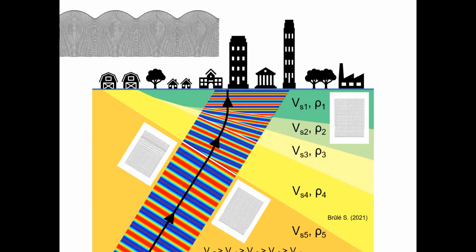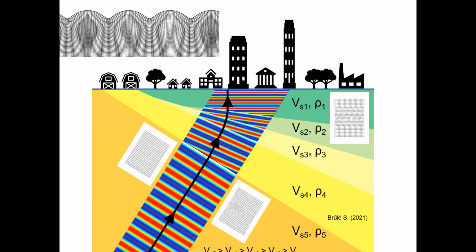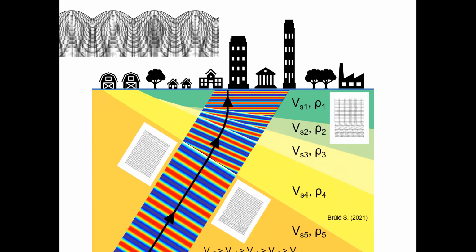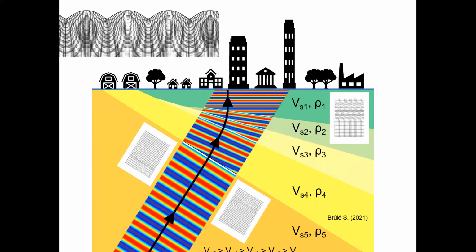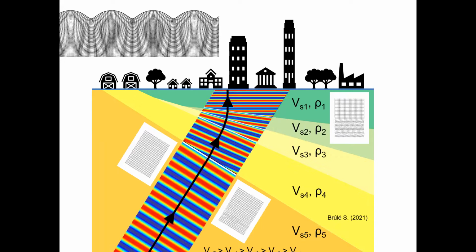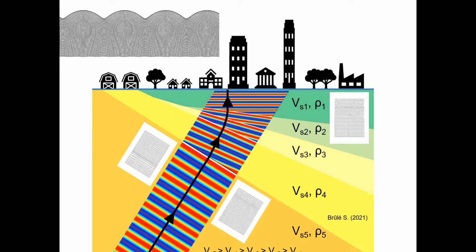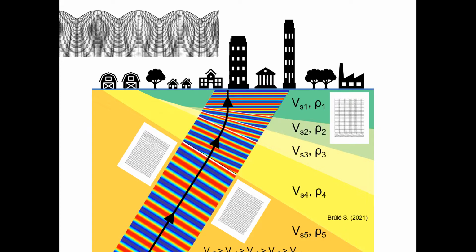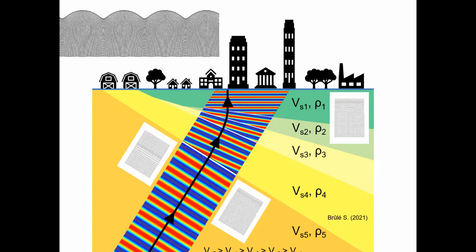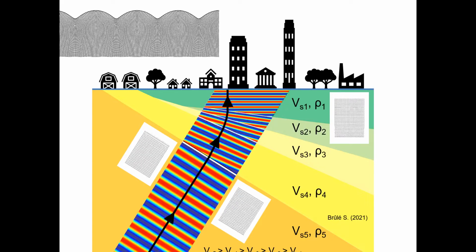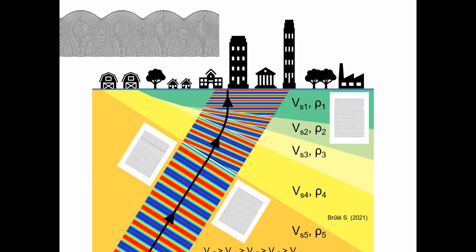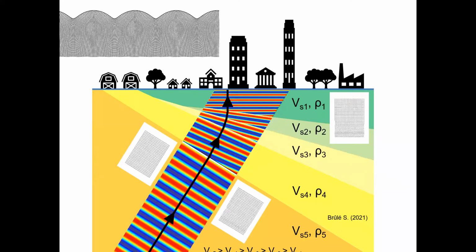This is the case of Mexico City, which had a very destructive earthquake in 1985. But the municipality of Mexico corrected the elastic design spectrum for all the elements, sometimes to 2 times the initial value from 30 years ago. So they had good behavior of the building if you have the good acceleration to put inside the model.